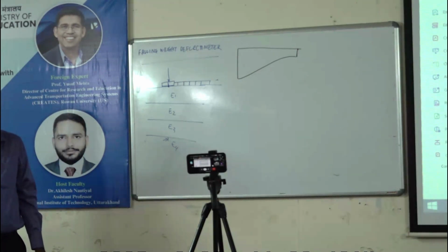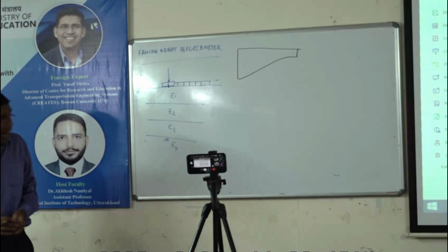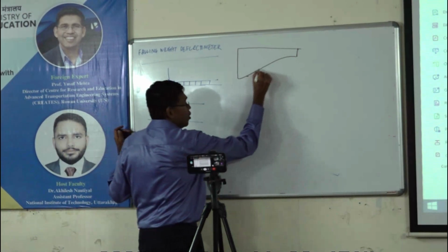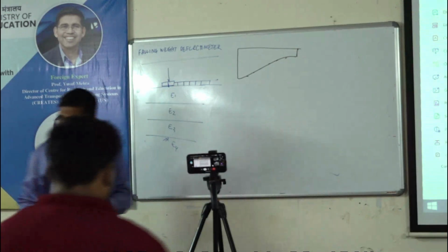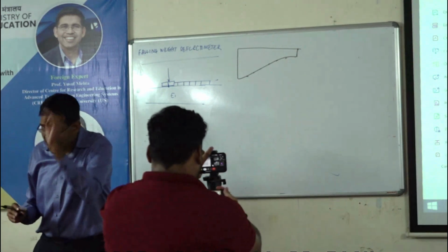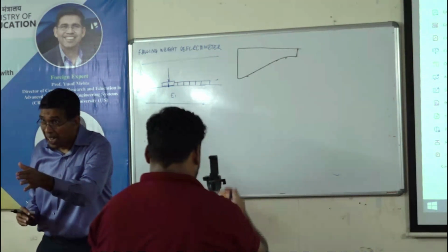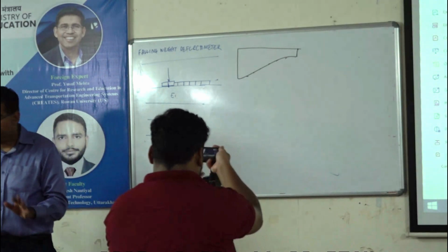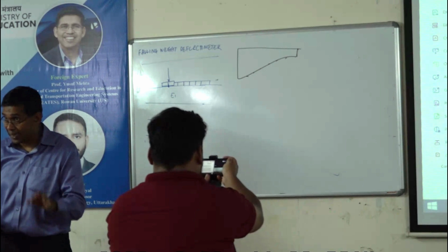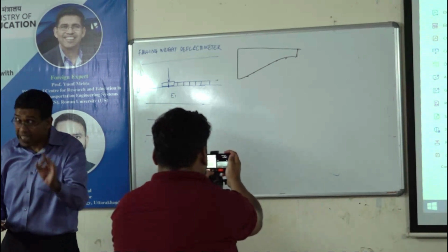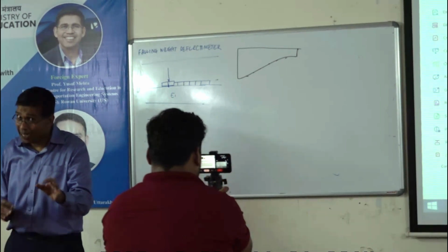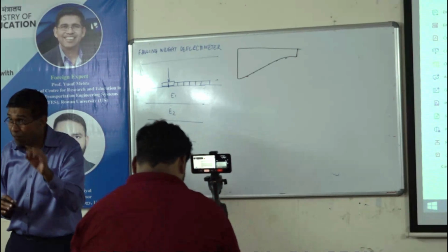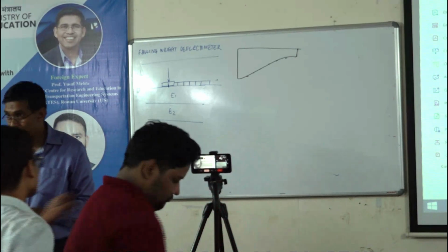Okay. Now my goal here is I have 7 deflections. Correct? And the instant I hit that load, at that instant, there was only one right value of E1, E2, E3, E4. Everybody agree on that? At that instant when I hit it, there was one E value. I have to be like Sherlock Holmes and try to find what those E values were. You see what I'm saying?